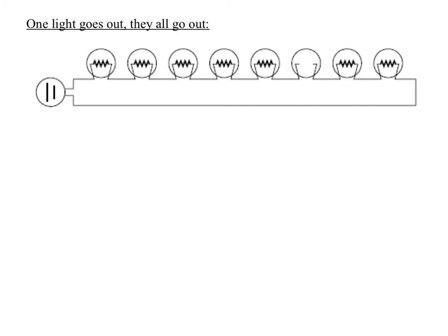The circuit is no longer closed. How can the electrons jump from the wire across without a filament? So imagine the bulb goes out, the filament breaks, there's no longer a closed circuit. Okay? Is that clear? The minute any bulb goes out or any resistor goes out in series, it's no longer a closed circuit, so all of the bulbs are going to go out.